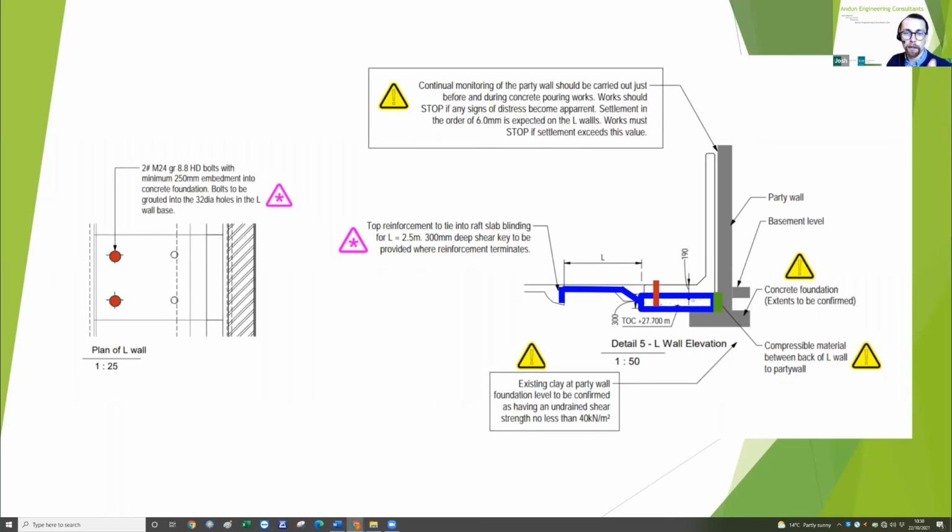The foundation from the party wall was also checked because of the increase in loading underneath the stem from the overturning force. And the distance between the stem and the wall also had to be controlled to ensure that the stem did not load the wall upon the pouring of the concrete.